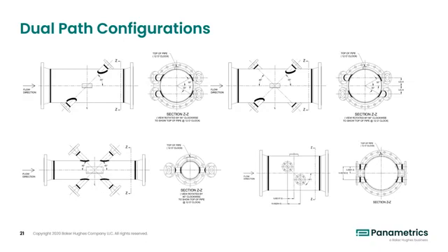When two channels are being utilized, one will read slightly positive, while the second channel will read slightly negative. The average of these two channels will then show that there is no true flow going through the pipe. A final advantage of multipath configurations is the ability to have a redundant system, allowing for measurement even if one channel is damaged or not reading properly.